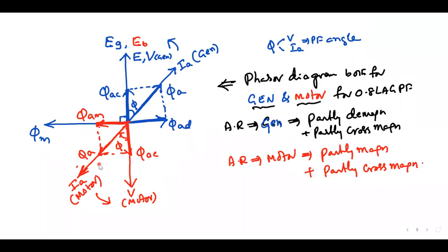Sir, when we are drawing the phasor diagram in the motor case, in the leading case, we will get that E value is more than V. Where? In motor. In motor, which power factor? Leading power factor. Yes, E will be more.